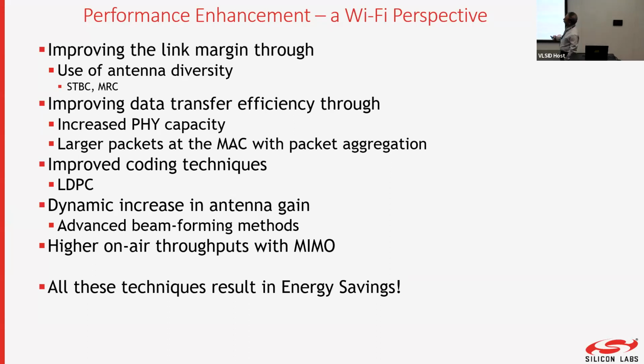You can also improve your capacity, have higher modulation schemes. Wi-Fi is doing that. Every new generation of Wi-Fi gives you more data capacity. It not only gives you higher data rate, but also improves your average power consumption. You can eliminate overhead by using a large packet with a small header. That's something called aggregation. From Wi-Fi 4 onwards, packets are aggregated in Wi-Fi. Before Wi-Fi 4 or 11N, aggregation wasn't there. It also improved with better coding techniques, LDPC instead of convolutional codes.